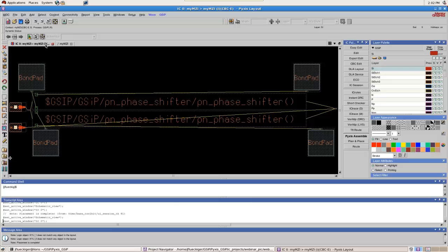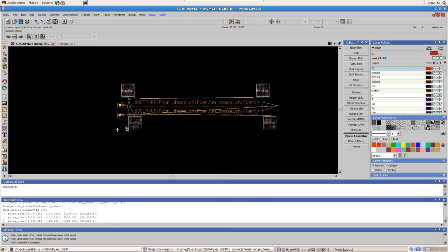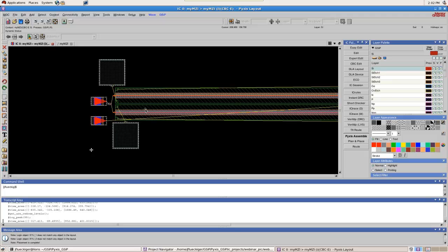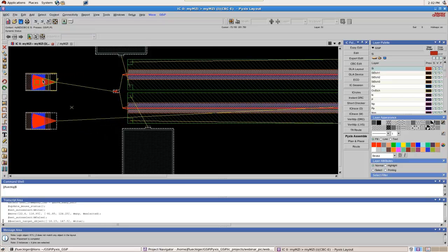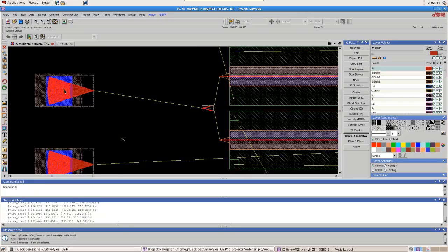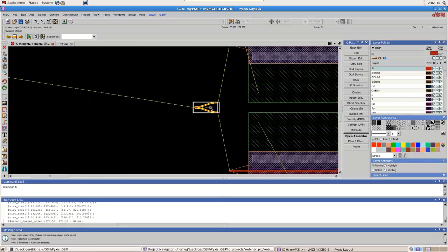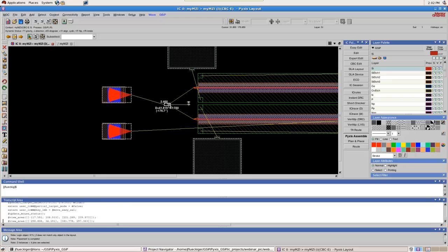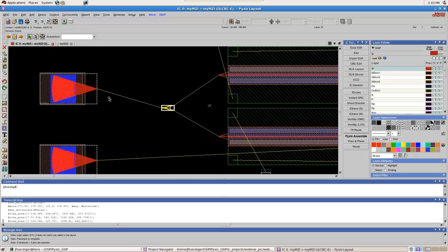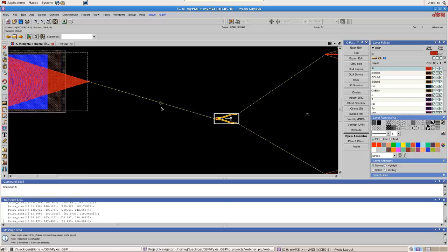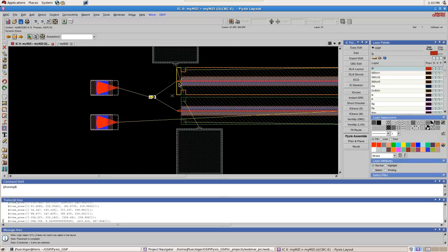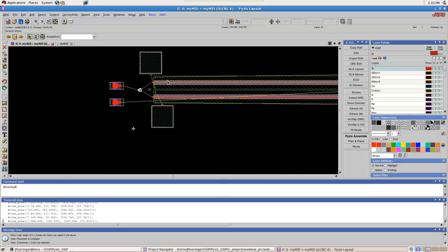Now, when they're placed in the layout, they're somehow arranged as they were in the schematic editor. So here we can zoom in and see the grating coupler, for example. So we're going to go there. So you can place them properly, and as you're moving them around and you put waveguides later, this is going to have an effect on your simulation. This is our Y branch. Notice that we're not connected to waveguides yet. We are just using nets information that came from the schematic. Later on, we're going to add the waveguides. We also have the two phase shifters and the electrical pad.